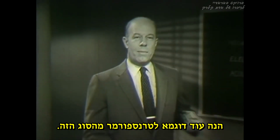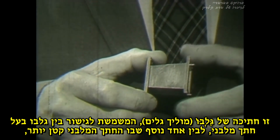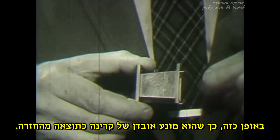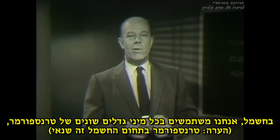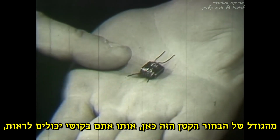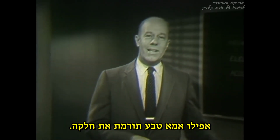Here is another example of a tapered section transformer. It is a piece of waveguide used to couple a section of rectangular cross-section waveguide to another one of a smaller cross-section in such a way as to prevent the reflective loss of radiation. In electricity, we employ transformers ranging all the way in size from this little fellow you can scarcely see, clear up to the big transformers almost as big as houses that you find in hydroelectric stations. Even nature herself is in there pitching.